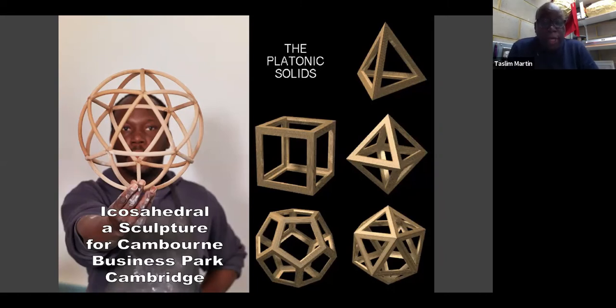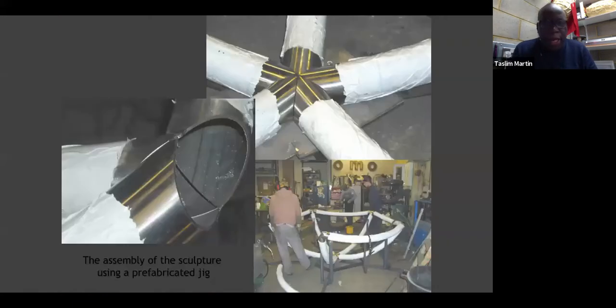This also taught me a lot about how I would go about making the actual real thing. This is quite a simple shape, but it relies rather heavily on one module, 20 arcs with a prescribed bird's mouth mitre on each end, and it needs to go together really rather accurately.